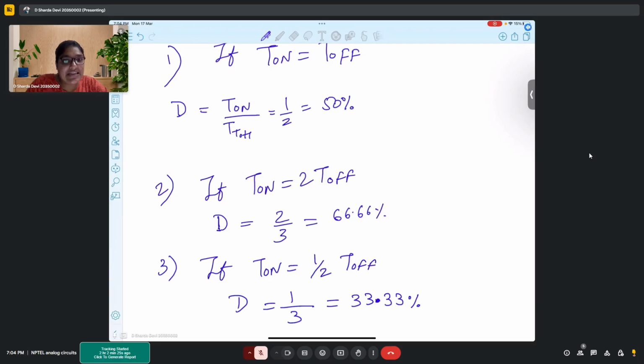But when the resistor values are equal, it is cancelled out completely, so there is no possibility at all. That is why in one case it will oscillate, in the other case it will not. That is what I could analyze, and I finished that day with that statement. So maybe you can look into it because that analysis is already there.